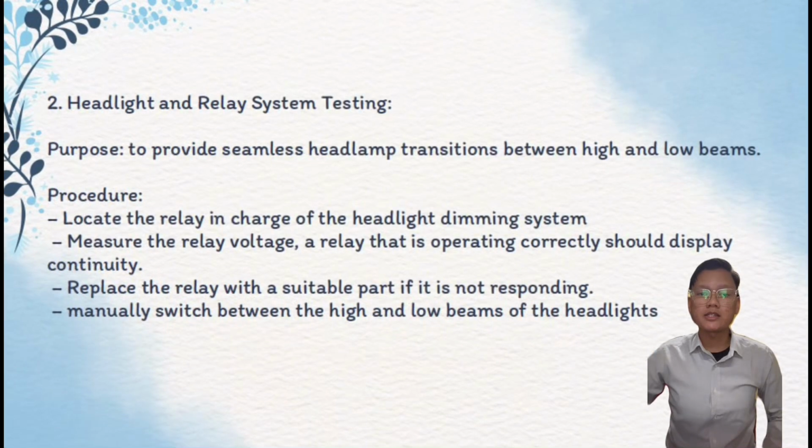Headlight and relay system testing. The purpose is to provide seamless headlamp transition between high and low beams. The procedure is: locate the relay in charge of the headlight dimming system by opening the relay box.